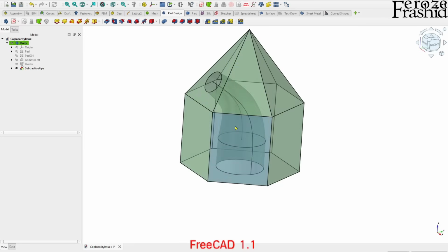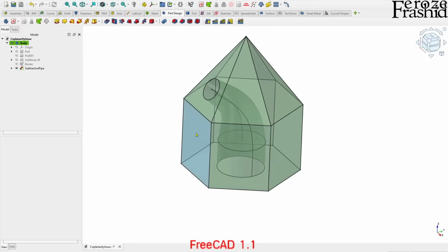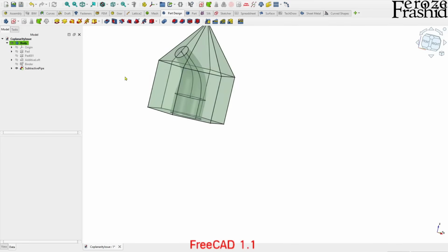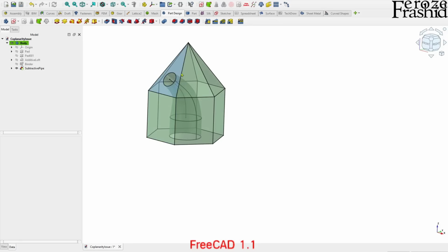So we could have started our model with only 1/6 of what we built. Since we already built everything here, I don't want to go back and rebuild everything. What I'll do is pocket the rest of the model and keep only 1/6 of it.